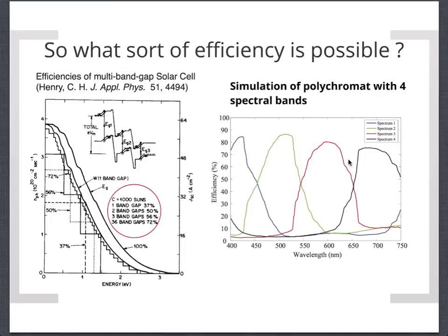Is there a certain distance away from the solar cells that it has to be? In this case, it's like 200 millimeters, which is a pretty large distance. But if you decrease the pixel width, which I showed you was 3 micrometers, then you can also decrease the propagation distance. We have a design where you can put the polychromator at a couple of millimeters, but for that you need a pixel width of about 1 micron.